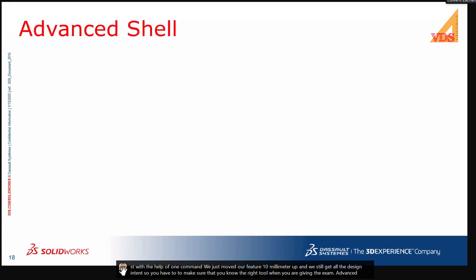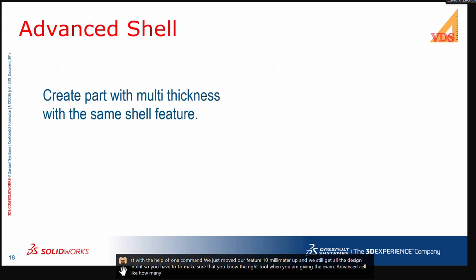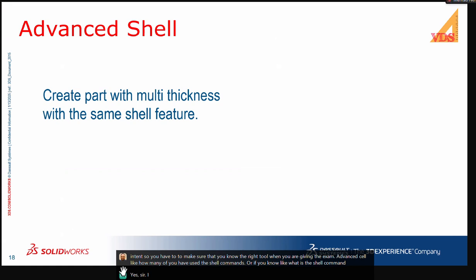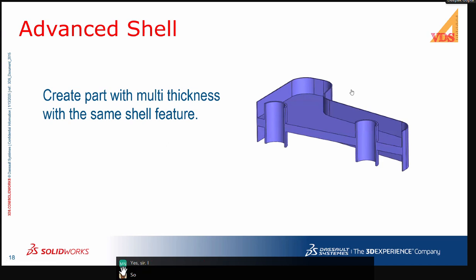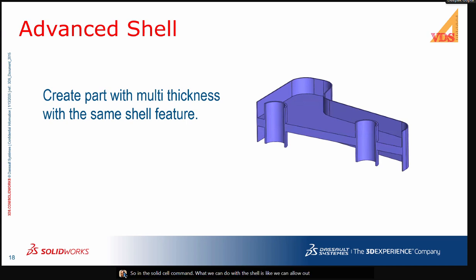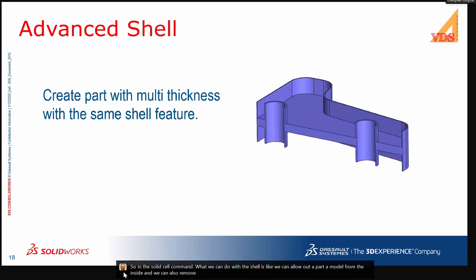Advanced shell. How many of you have used the shell command, or know what the shell command is? Yes, sir, I have used it. In SolidWorks, with the shell command we can hollow out a model from the inside, and we can also remove any particular face we want.